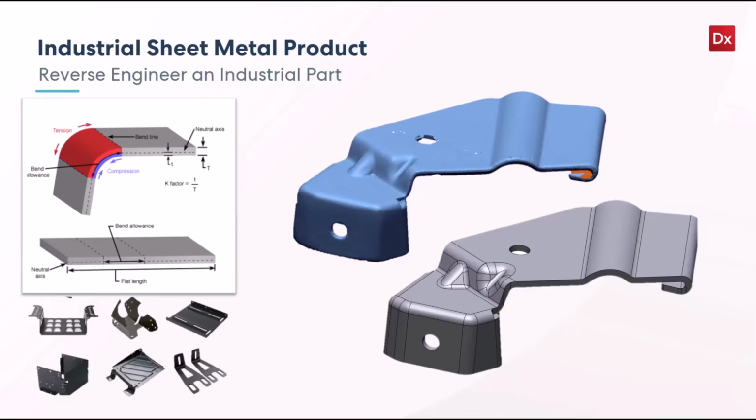So I figured I would highlight it on today's webinar. In general, when we have sheet metal parts that we model inside of Design X, we do model them as a solid. And again, this is like a stamped out sheet metal part too. This has got a few different stages. It looks like it was stamped and then bent afterwards. But what we tend to do is model that as a solid part and then do the other features, as far as flattening and stuff, inside of the CAD software. That is the approach that we generally take.